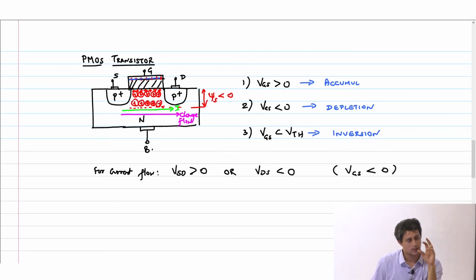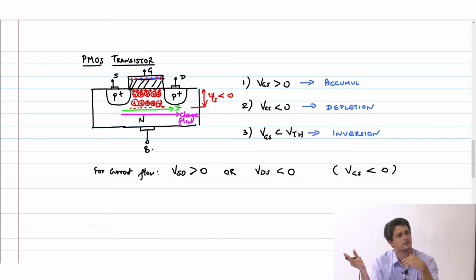Like I told you earlier, even for the NMOS transistor, if I give you just the device and ask you what is the source and what is the drain, I have no idea. You have to tell me what potential you apply. Once you apply the potential, in a PMOS transistor, the higher side is the source, because that is sourcing the charges and the drain is draining out the charges. It is just a convention and a definition. Of course, if I reverse this potential and apply higher there, by definition that will become the source, that's all.